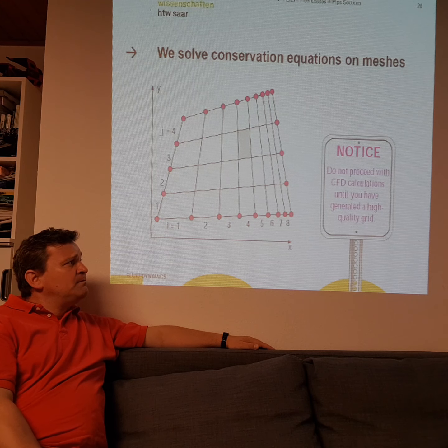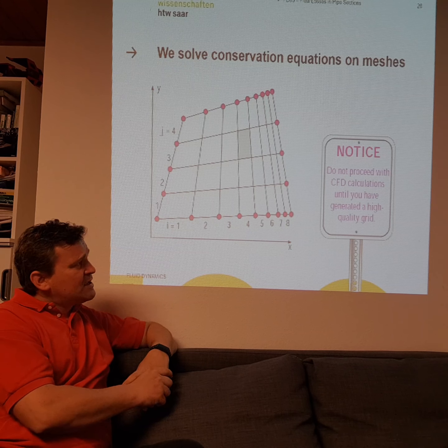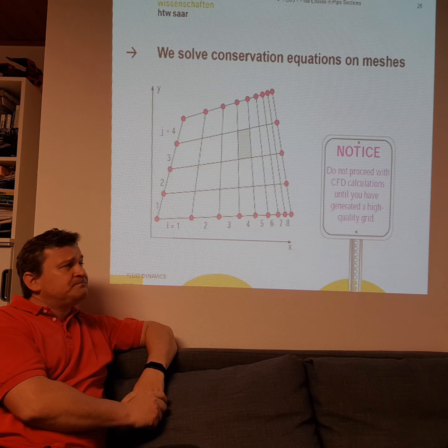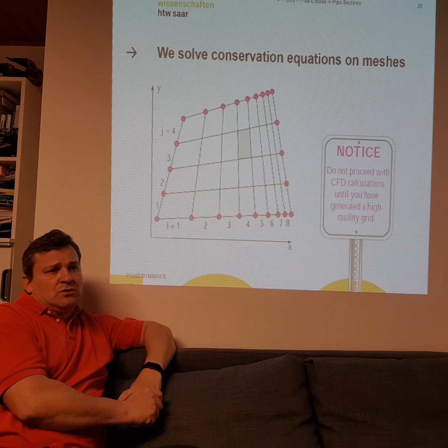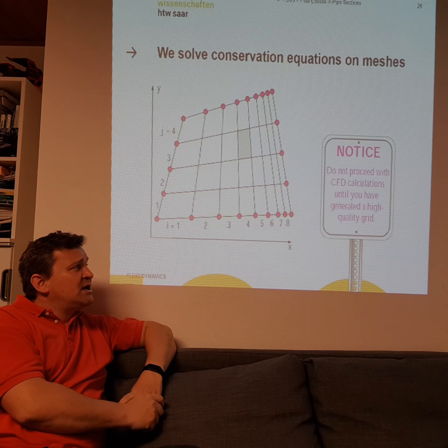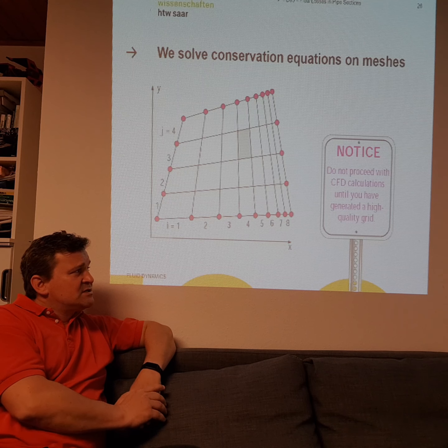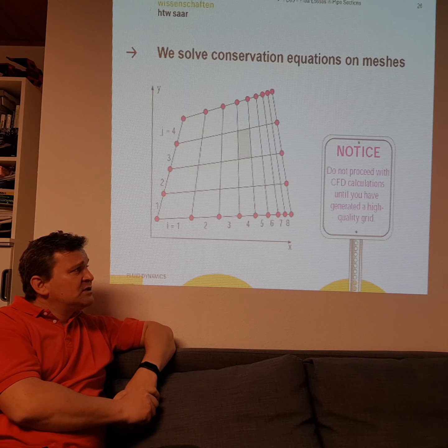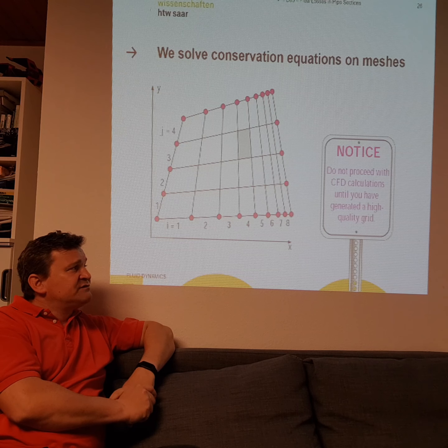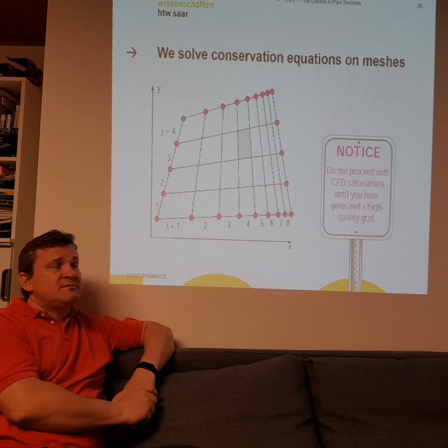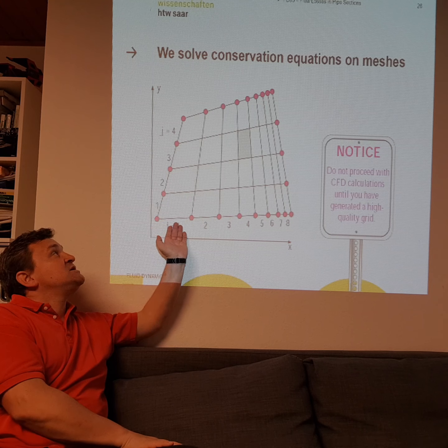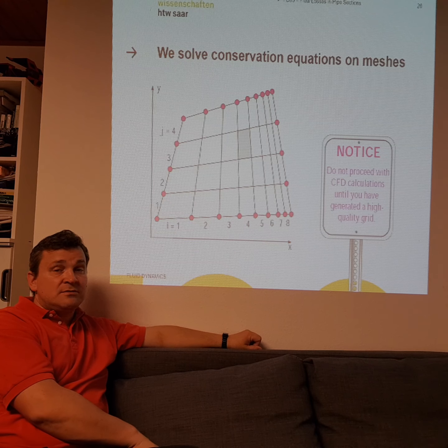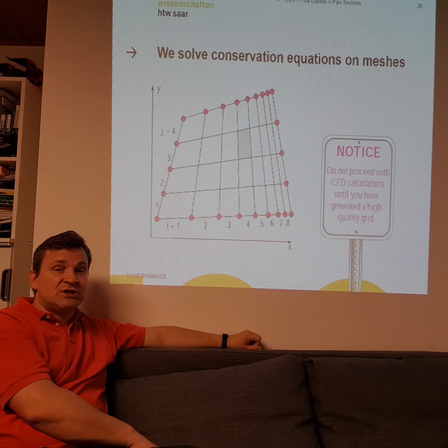But if you look back on CFD a bit, and you're also already familiar with this tool under CFX, there's always something I want to mention. Do not proceed with CFD calculations until you have generated a high quality mesh. Here again you see a so-called Cartesian mesh, an example for a mesh.